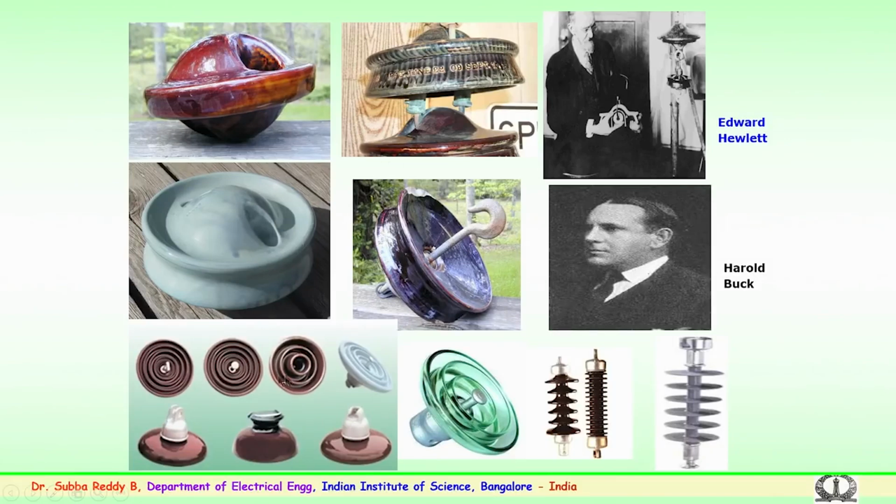These are of recent origin, being used for the extra high voltage and ultra high voltage regions. So, you can see basic ceramic insulators or a glass insulator. Glass is popularly used in Europe because of material availability. Mechanical and electrical performance of ceramic and glass insulators is the same. We will look briefly into the manufacturing process in due course. These are again various types of ceramic insulators used for railway traction, bushings, for equipment, and so on and so forth.